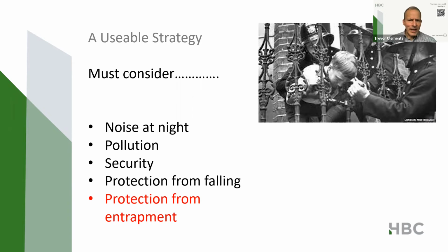So they shouldn't allow the passage of a 100 millimeter diameter sphere, even. All those little pin-headed children there with the tiny heads, we don't want them getting their head stuck. And also any hole more than 8 millimeters must be at least 25 millimeters and must not taper. So never mind heads, we don't want any fingers getting caught in there as well.